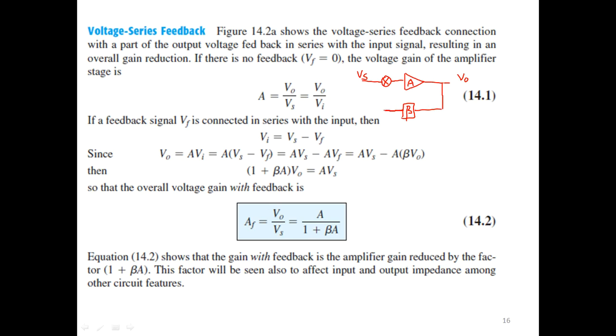and let us give the output of the feedback network to the mixer circuit, so that Vi becomes our actual input to the amplifier, and Vi is the sum of Vs and Vf, where Vf is the feedback voltage. Depending upon the phase of the feedback voltage, the magnitude of the input voltage to the amplifier, Vi, depends on it. So now let us look at the things. What does the statement say? It says if there is no feedback, then obviously Vf will be 0.